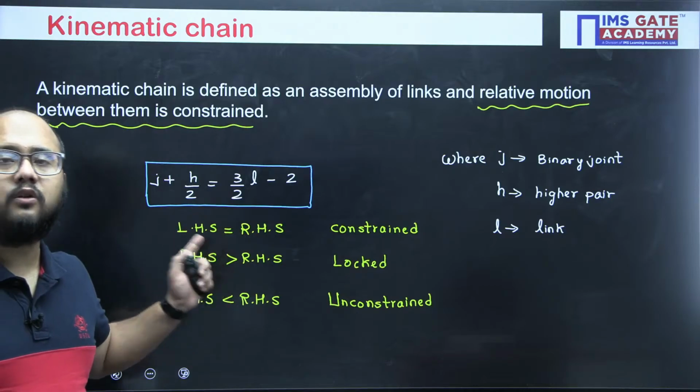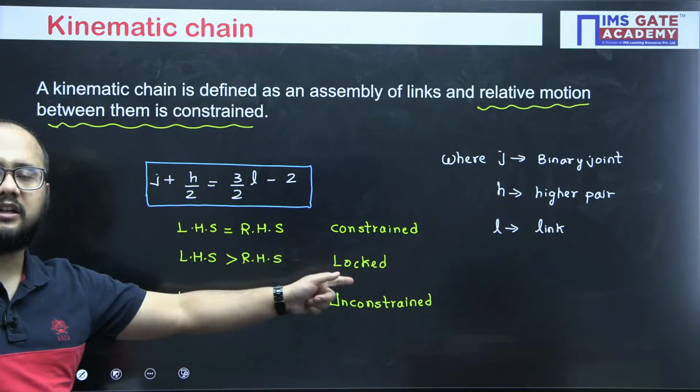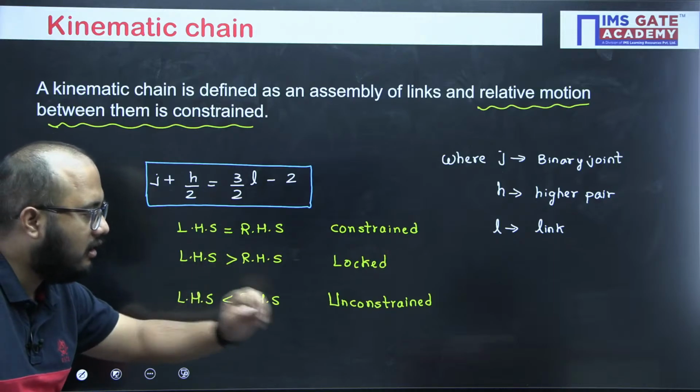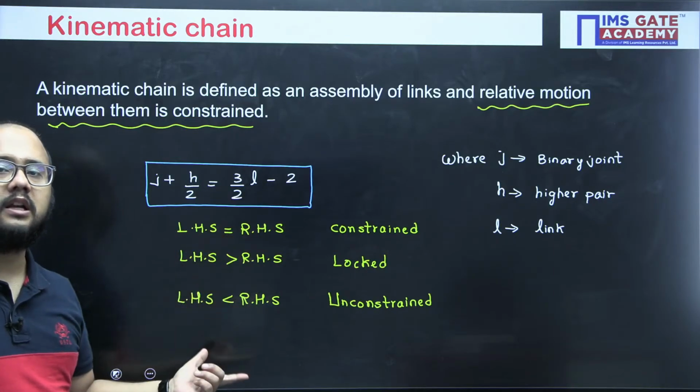Using this relation, you can tell whether the chain is a constrained kinematic chain, or a locked chain, or an unconstrained chain.